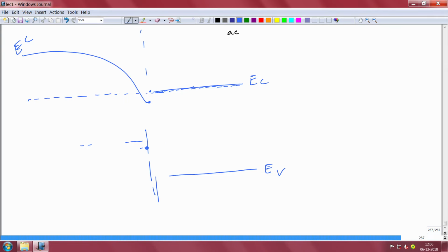So this is the Fermi level eventually, the global Fermi level that will form here, and this point was the valence band of the semiconductor. Far away from the junction it has to be the same, so it goes like this. The band gap has to be the same everywhere on the left side. It has to go like that. The band gap is the same of course everywhere. Far away from the junction, EC minus EF minus EV has to be constant, and there is a huge depletion here. You can see the whole band gap.